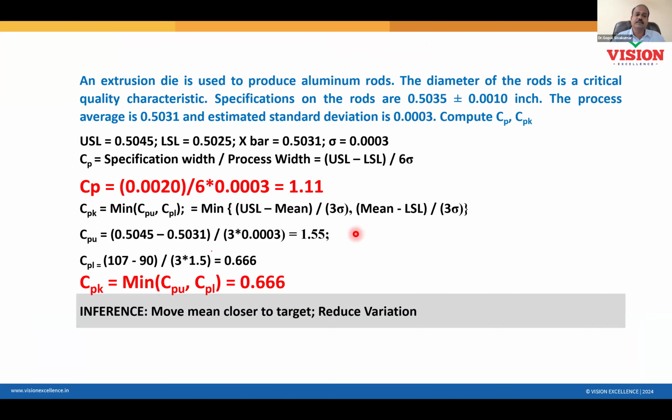All right. So another scenario. Cp equal to 1.11, Cpk equal to 0.66. What is your conclusion now? Your process is capable, consistent? The process doesn't have the potential to be capable, so some modification in the process is required. The process doesn't have the capability, meaning people demonstrate poor control. And so the control must improve.